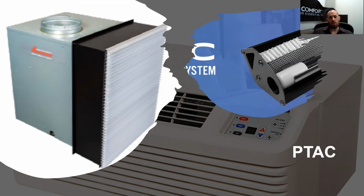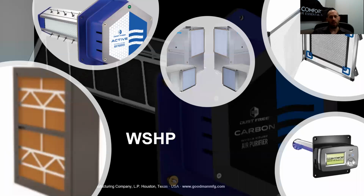PTACs and VTACs are small, but we make an air purifier unit specifically designed to fit in those units. They work really well. Water source heat pumps. Here you get a lot of filtration options. You can use a media air cleaner. You can use a hybrid. Often we go to the dual stacked filter, kind of designed for those large openings. Based on the ductwork, you can use a normal air purifier or a UV light, or you can put that UV light inside the unit by the coil, depending on your configuration.